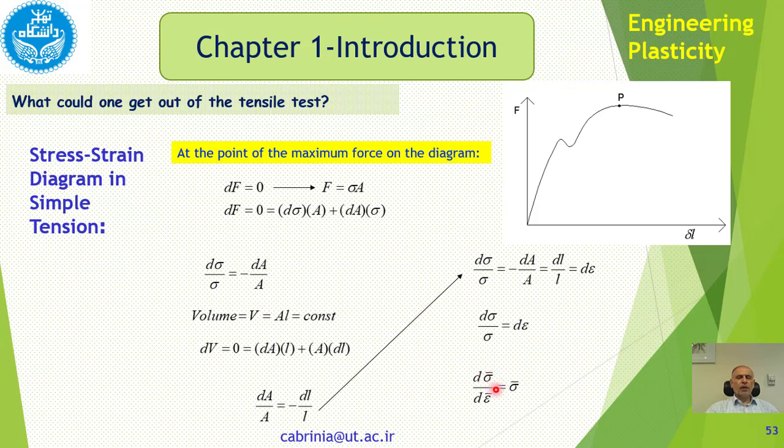It means that if a body is acted upon by different loads in different directions, we get different stresses. But we can average them out by writing out sigma bar. So this sigma bar is called effective or representative or average stress. Also, epsilon bar is the same thing. Therefore, this one is the same as this. This is for the tensile test. This is for any plastic deformation. Okay, the sigma bar, the epsilon bar.